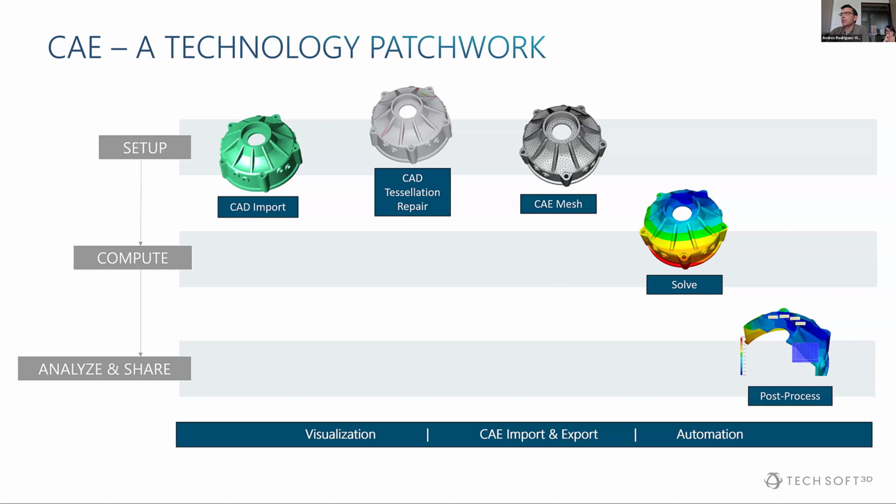That CAD representation, to get into the finite element world, has to be transformed into a mesh. To do that, the process will rely on the tessellation of the BREP. More often than not, those tessellations are not completely compliant.